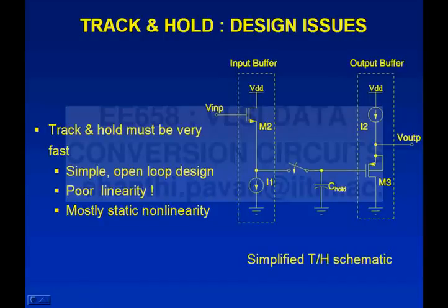So if you put the NMOS transistor here and the PMOS buffer here, what would happen is that when this buffer is driving the large capacitive load here, the voltage on the hold capacitor will get perturbed simply because of some kind of Miller effect. Because if this changes by delta V, this will not change by the same amount, so some amount of charge will get sucked through that.